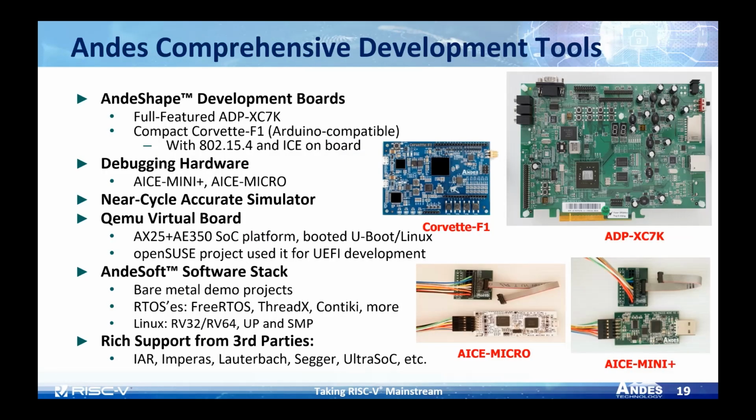That's the hardware I have mentioned before. You see we have various FPGA boards depending on what you're developing, from a high-end FPGA board with DDR3 RAM on it, with SD card interfaces, VGA interfaces and sound, up to a lower one with wireless interface for low power networking.